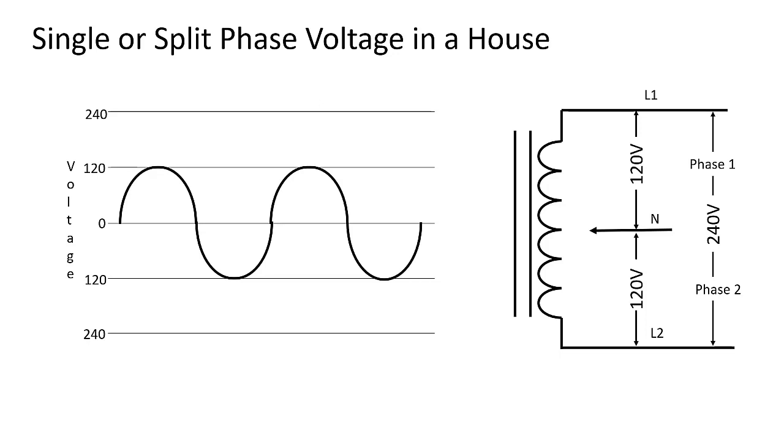The black wavy line is called a sine wave. It shows how much push and pull is present as electricity alternates back and forth. It starts on the left at 0 volts, it quickly climbs to 120 volts, then alternates back down through 0 volts to 120 volts again. The generator at the power station does this push-pull 60 times per second.